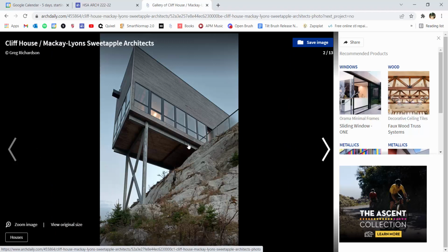These beams right here. The easiest way for me to draw those in would be looking at this elevation, right? The same way that I drew the I shape for this column, it would be easiest for me to draw that I shape in elevation and sweep or extrude that back. So this is an instance where I would want to go into my drawing, create a reference plane, and draw that I-beam on the reference plane.